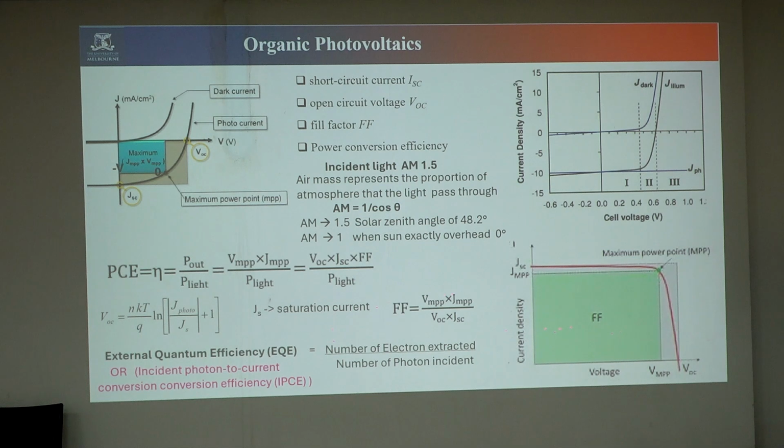You know that. So anything you can do, current into voltage, we already know the power, and input light is also power. So here this is the short circuit current and this is VOC. The fill factor is not like this: normally when you get this type of exponential curve, we ideally want it to be flat and then suddenly drop because of recombination.